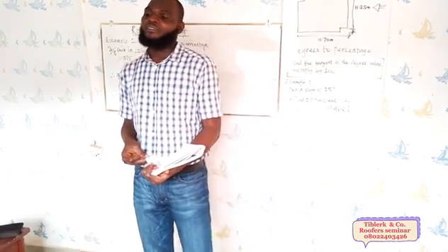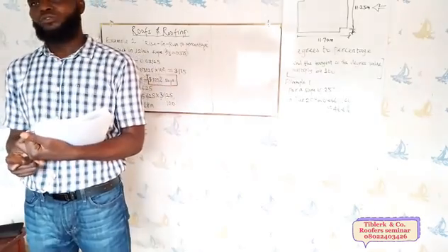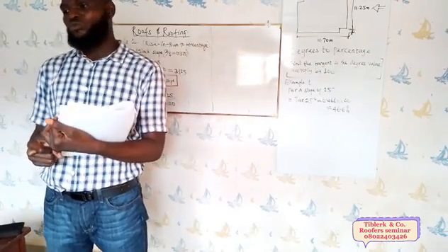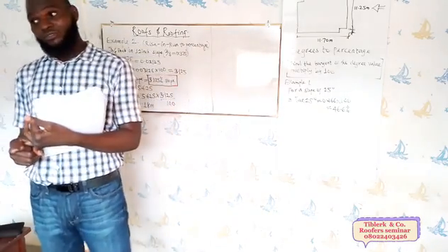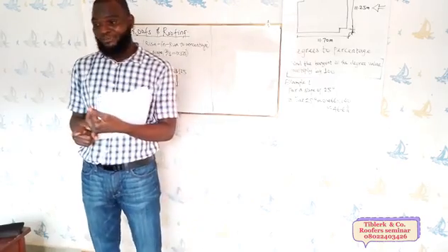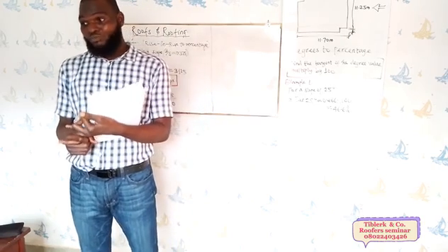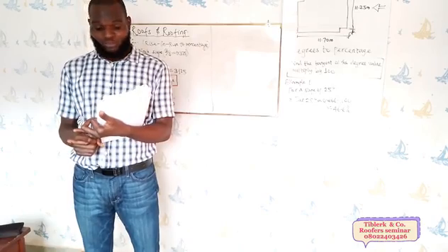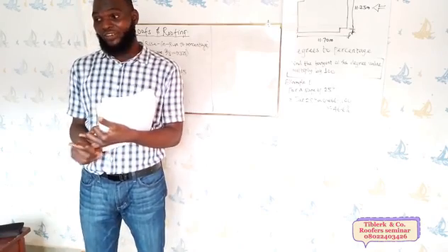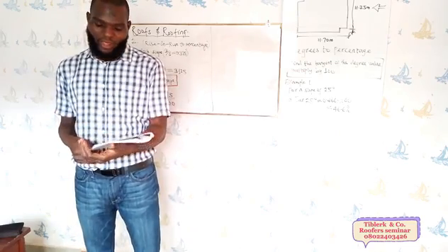But number one, even right from the construction, the ease of construction will not be there anymore, which is what the buildability concept is all about. Also, the maintainability, when it comes to maintaining it, then you now know the resultant effect of having unnecessary height.